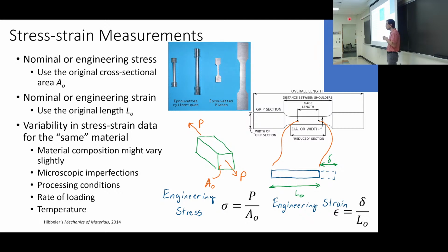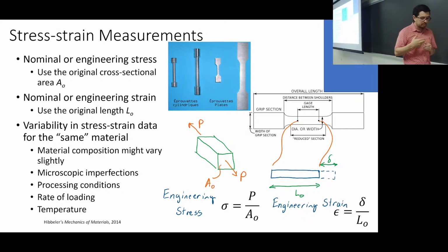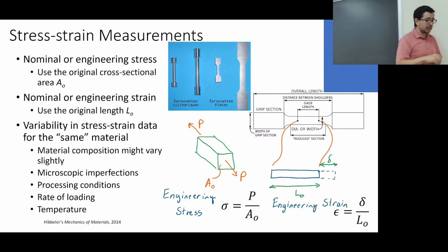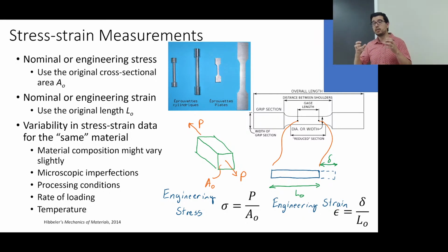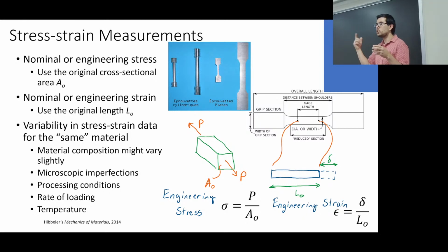Okay, and that's called stress. That's from a stress concentrator. Usually, stress concentrators are not too big a deal. Not as big a deal with static loading, okay, meaning we go one time. But in the cases where you have vibration or fatigue, where you're going over and over again, that's where the stress concentrators really play a role.